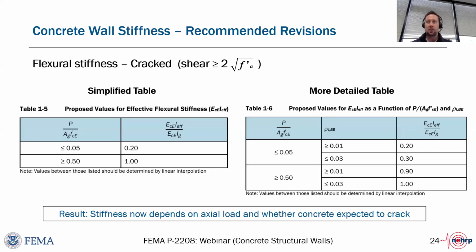So some of those changes on the 318 side had to do with expected material properties versus minimum specified, which is what new code uses. Those issues don't exist here in existing because we tend to try to target the median expected strength for existing. So part of that goes away, but there were some other components that arguably could feed in here. But currently, this is based on the same procedure as ACI 318-19.